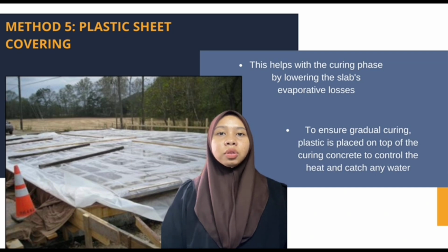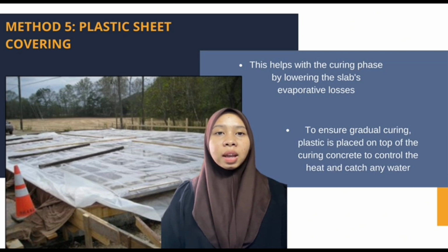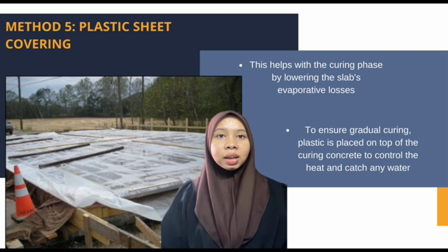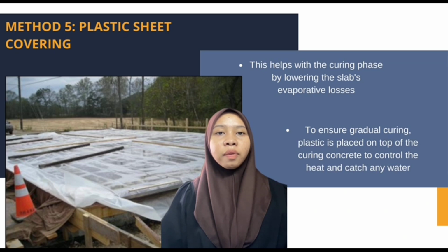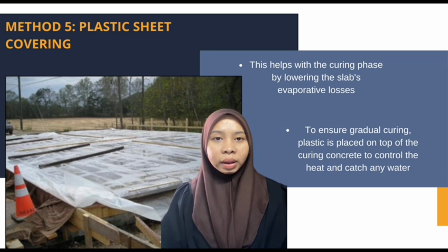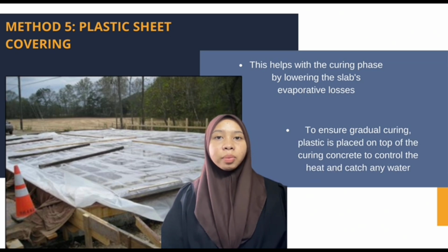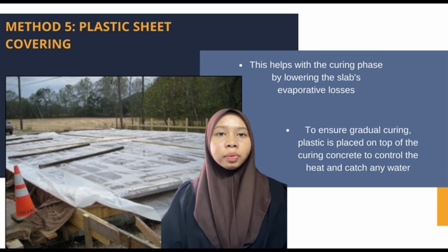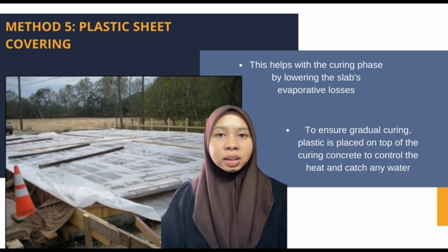It produces a first set that is entirely coated in a layer of plastic. This helps with the curing pace by lowering the slab's evaporative loss. In this method, temperature has a big influence. Therefore, the plastic covering must be selected accordingly.